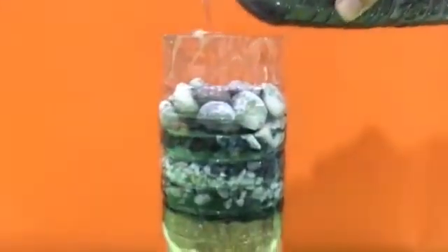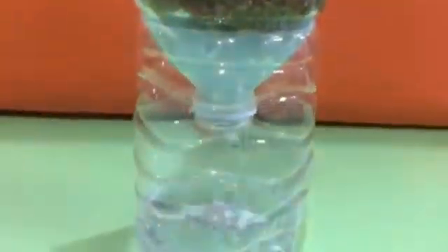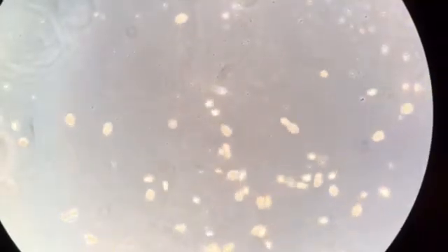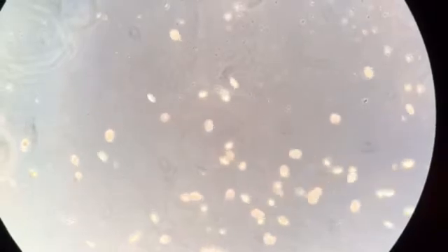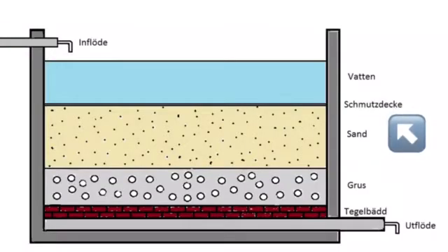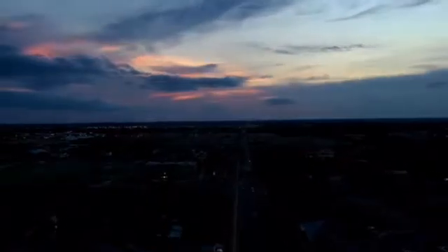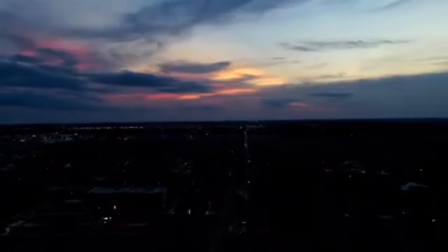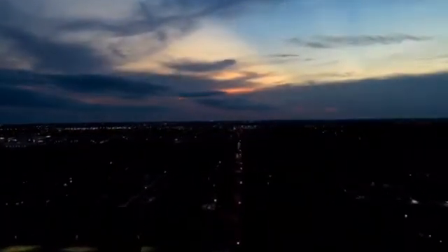Slow sand filters, on the other hand, focus more on removing biological contaminants, mainly protozoa and bacteria, through a biological layer called the Schmutzdecke. The microbiota of this layer helps to eliminate the biological contaminants. Now, let's take a look back at how the sand filter was created.